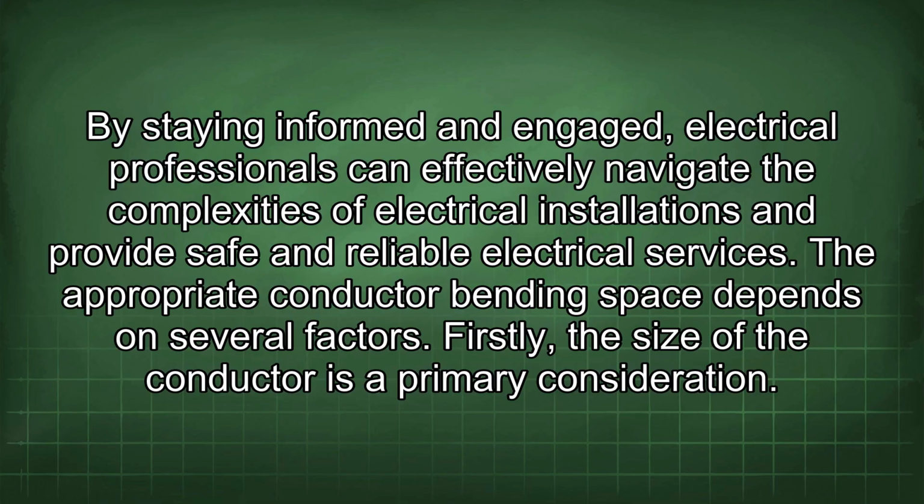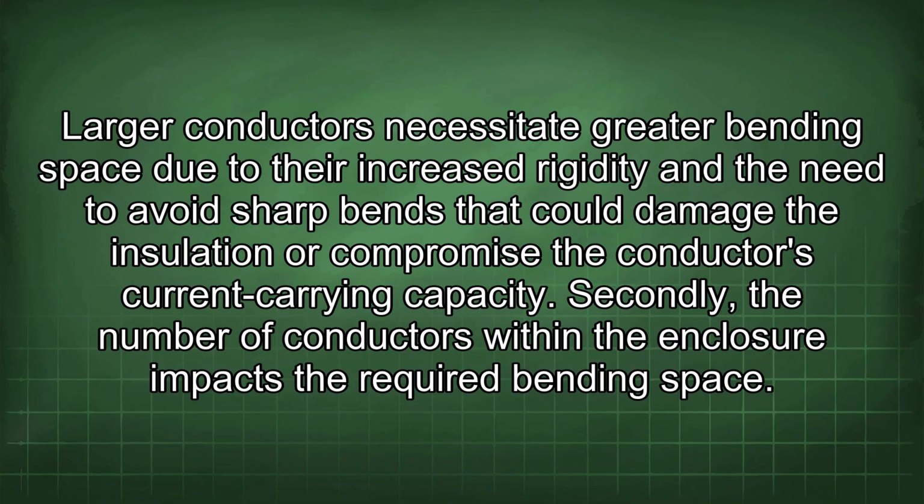The appropriate conductor bending space depends on several factors. Firstly, the size of the conductor is a primary consideration. Larger conductors necessitate greater bending space due to their increased rigidity and the need to avoid sharp bends that could damage the insulation or compromise the conductor's current carrying capacity.